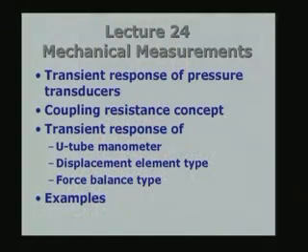So, the coupling resistance is like the convective resistance or the film resistance in the case of heat transfer from a system to surroundings. And then of course, there is an inherent inertia of the system, like the mass specific heat product for a thermal system. The pressure transducer also has got an inertia. So, we are going to look at some of these issues and find out how to discuss or how to characterize the time response of various systems.